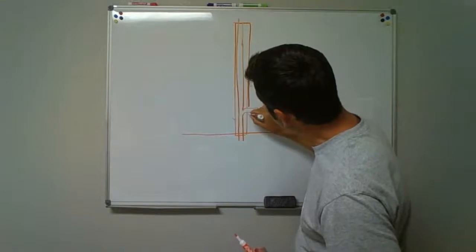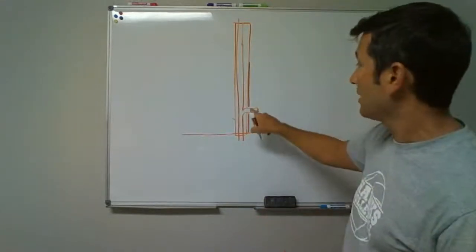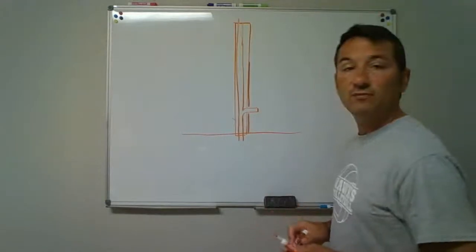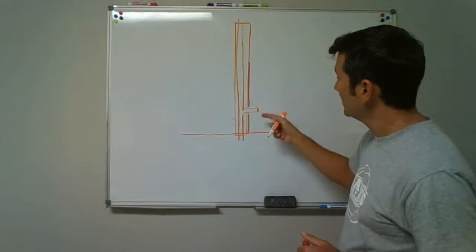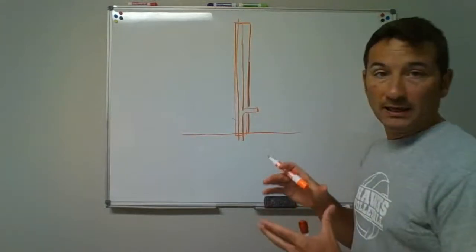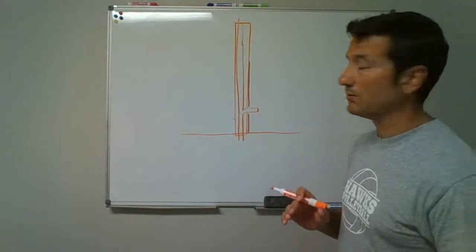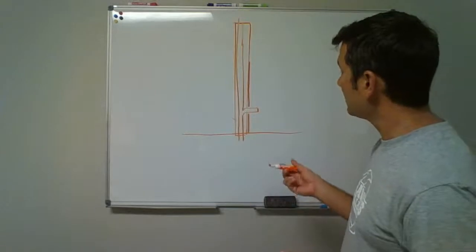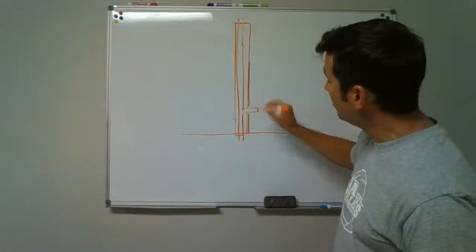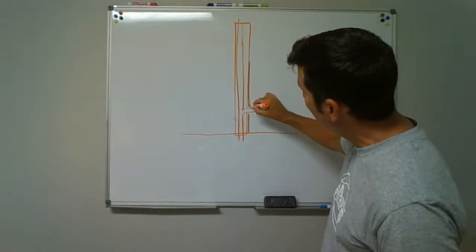There's the drywall, and it leaves a gap around where the pipe comes through. We've got to have those spaces cleaned off and sealed off. If it's too big of a hole, we need them to come back in and patch drywall around there with drywall compound and seal that off, to where it gets to the size that we'll end up putting a trim ring over this.